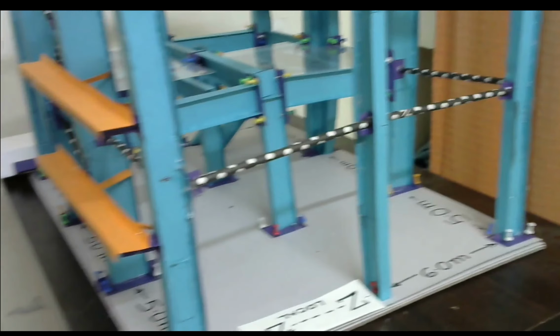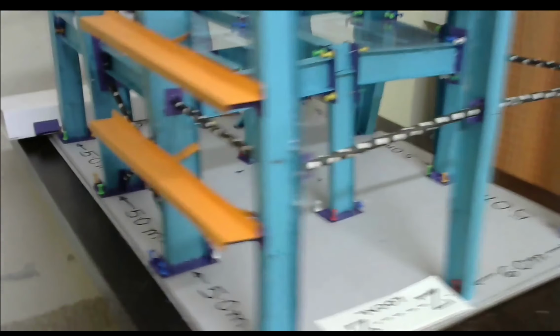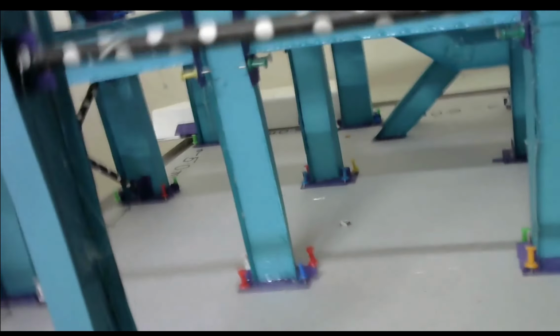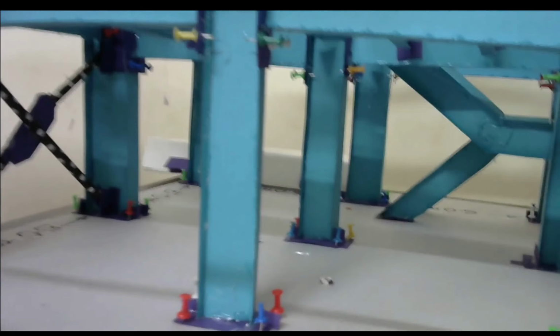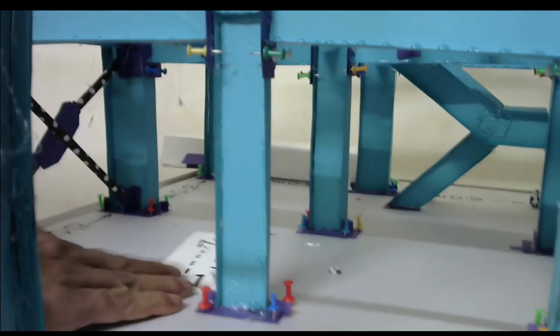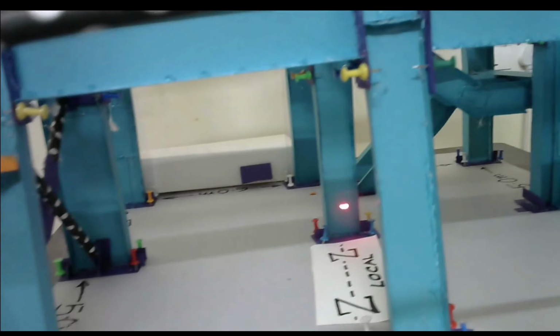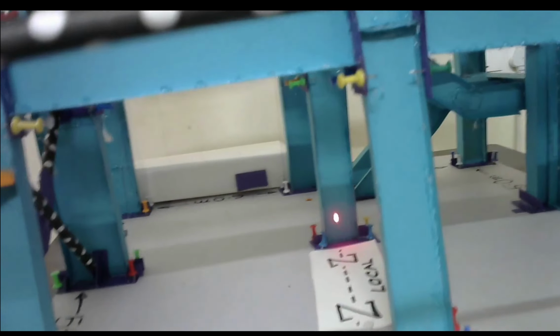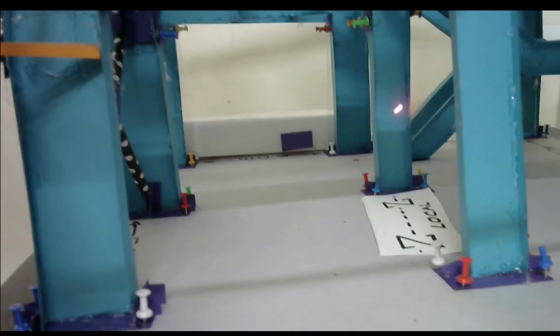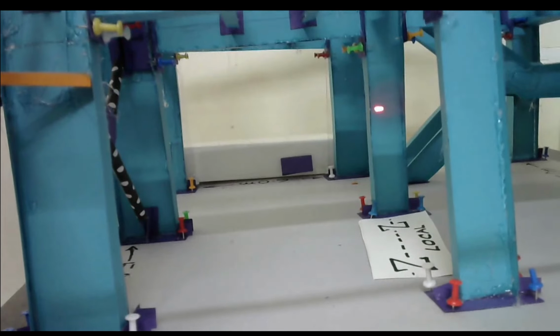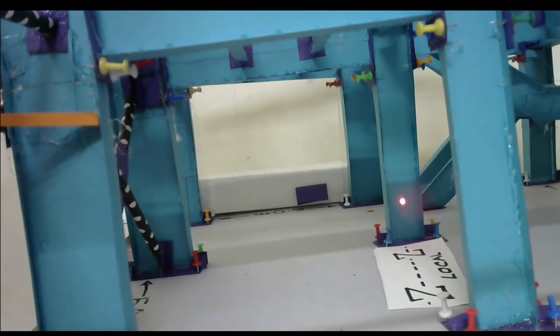Again for the other interior column here, if I put the local ZZ axis here, LX is 3, LY is 3, but LZ, it is along a sway frame, moment frame. So it is 3.6. So with this we covered all the parameters of the columns.